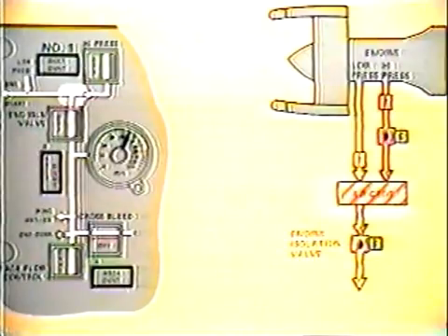Located just above the engine isolation valve is an ejector that mixes high-pressure bleed air and the low-pressure bleed air to satisfy pneumatic system requirements. High-pressure air will be mixed with low-pressure air at low engine power settings. High-pressure air will also be added to supply a higher temperature when using wing anti-icing.